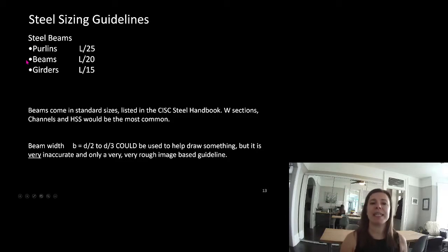Beams are the things that tend to be on the major grid lines. They are the things that are usually at the perimeter of our bays. If you want to think of it this way, they are usually the beam that is supporting our open web steel joists or purlins. They might also have metal deck on them, so don't let that distract you.